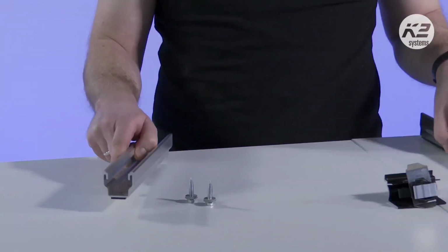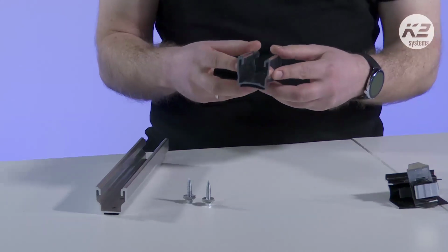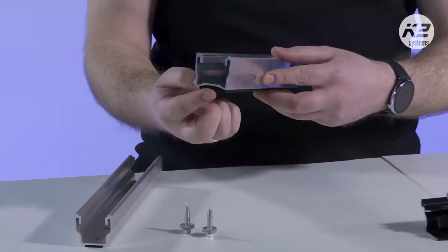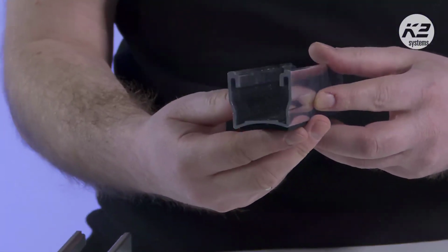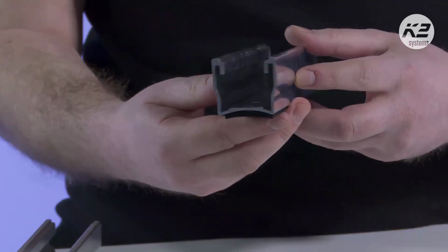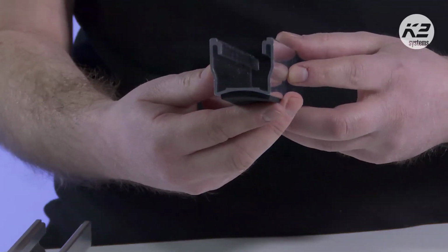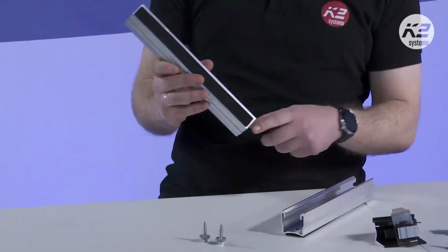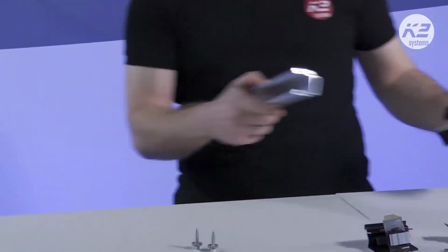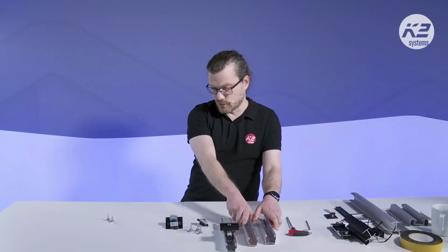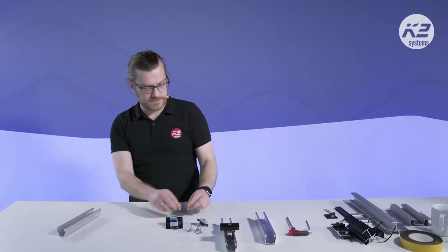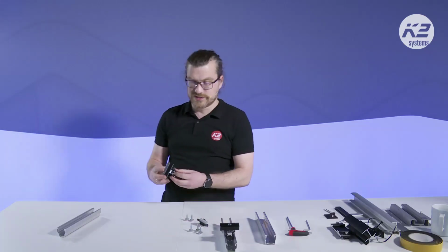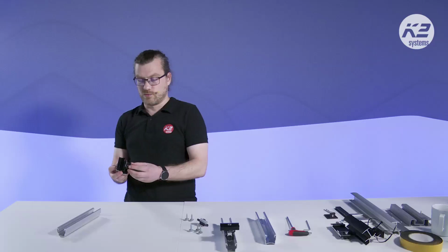If you have corrugated metal sheet, like waved form, we have this MultiRail 25 CSM. You will see that it's a special form. It's rounded. Let me get the cam. Here we go. It's rounded. This is our EPDM sealing, protecting your trapezoidal sheet, keeping it watertight. So only one component is also the same we use in our pitched roofs. It's our mid clamp.